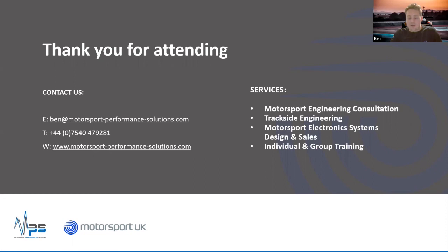I assume that KPI stands for key performance indicator, as it does in other sports. So yes, there are metrics you can put on these things, and I use one called coast time, which is a little counter that counts up when the driver does. The transition between the driver should be accelerating and then almost simultaneously coming off the accelerator and applying the brake.